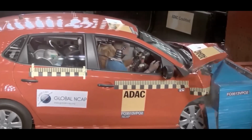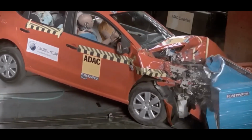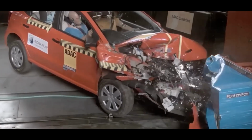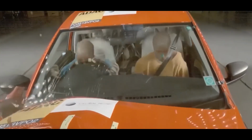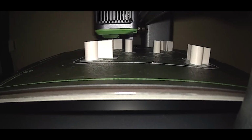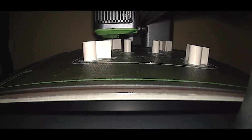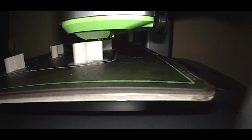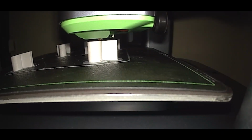Structural frame. The primary structure consisted of lightweight 3D printed parts combined with rod-guided motion systems. This provided controlled linear motion while minimizing unnecessary mass. Damping system. The damping subsystem used friction generated between sliding rods and the outer guide structure. Additional energy absorption was provided through memory foam compression at the front bumper. Together, these systems increased collision duration and reduced peak acceleration forces.